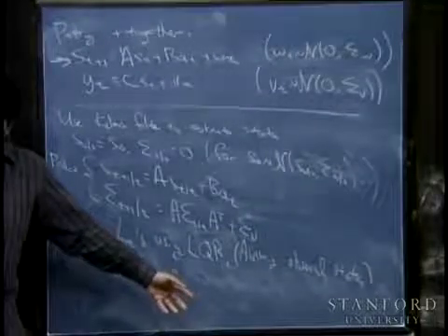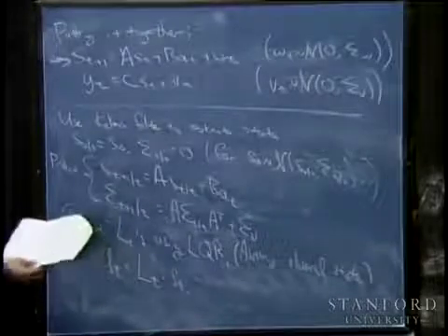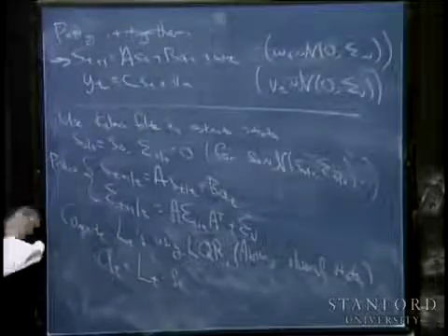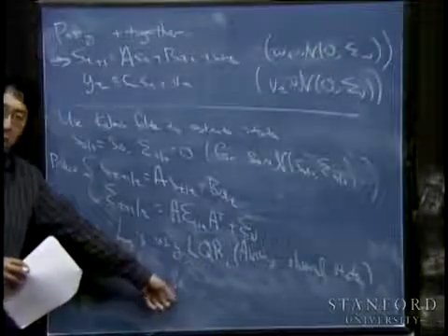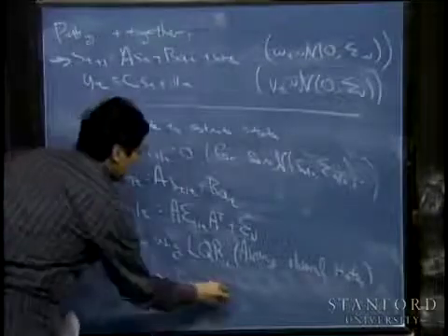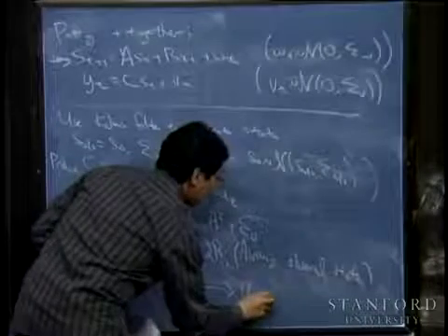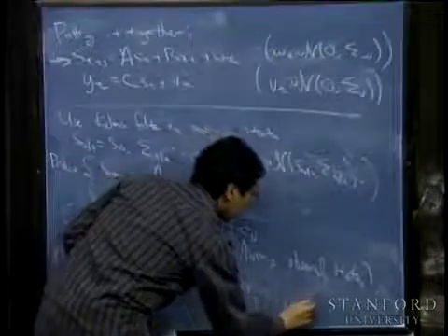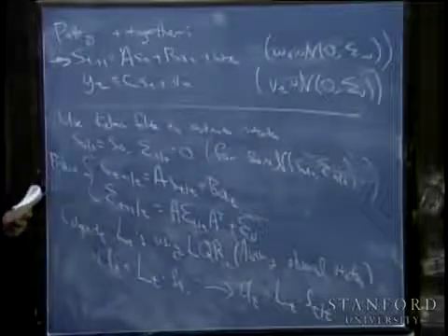And the very final step of LQG control is that, when you're actually flying a helicopter, you can't plug in the actual state, because in an LQG problem, you don't get to observe the state exactly. So what you do when you actually execute the policy is choose the action according to your best estimate of the state.